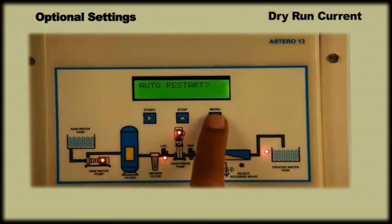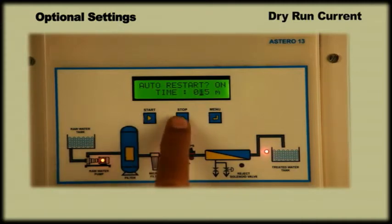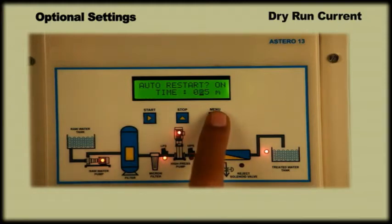By pressing Menu again, the display will show Auto Restart off. Now if you want to turn on the Auto Restart, use the Stop key to turn it on and press Menu. After turning it on, press the Menu key, and it will display the previously set Auto Restart time. That is, once the pump goes dry running, and if auto restart is on, then the motor starts automatically after the set time has elapsed. To exit, press the Menu key again.